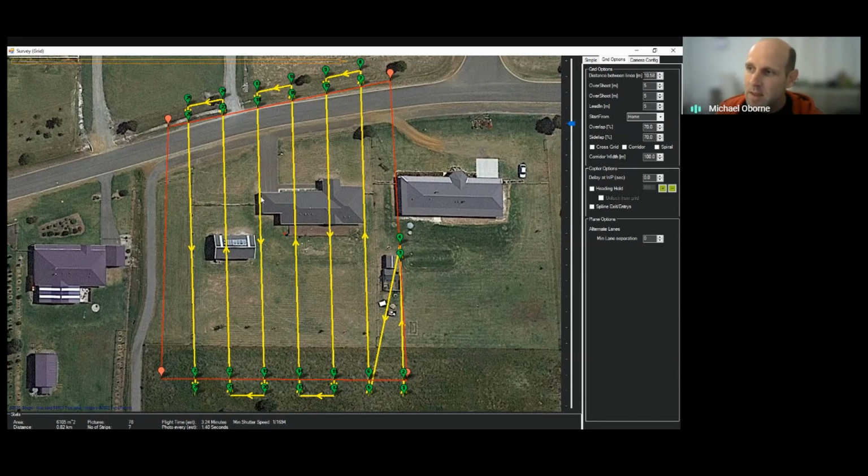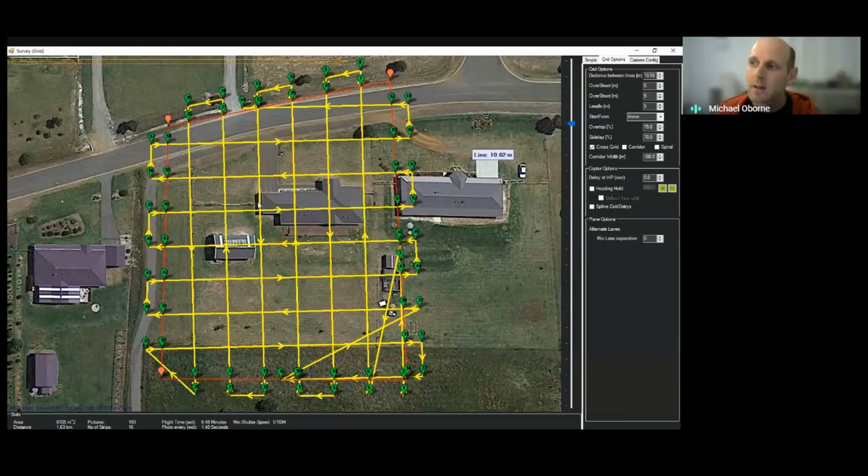The wall will only be oblique angled from this line and this line, so that'll be 3 shots of this flat wall. Whereas if I do it this way, I will get additional shots of that flat wall as well. So what it allows is a lot more points to allow a better reconstruction using photogrammetry software.